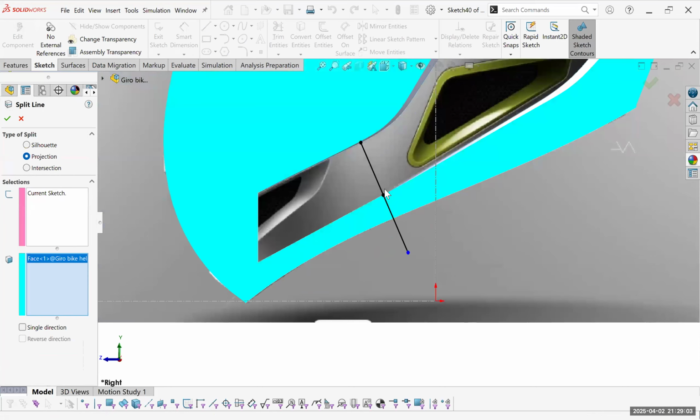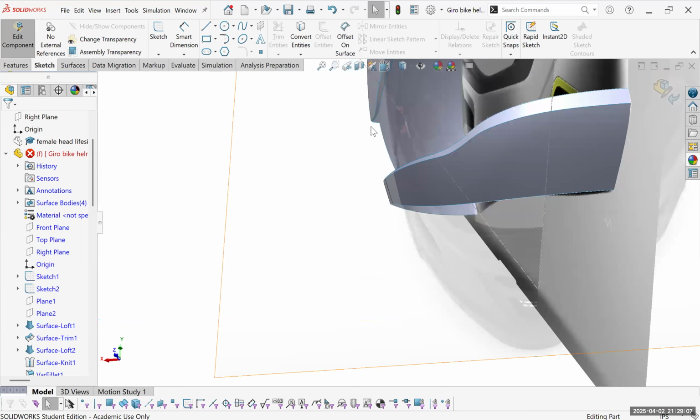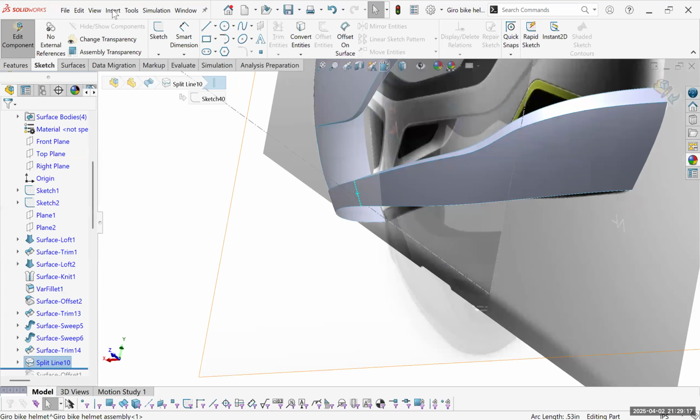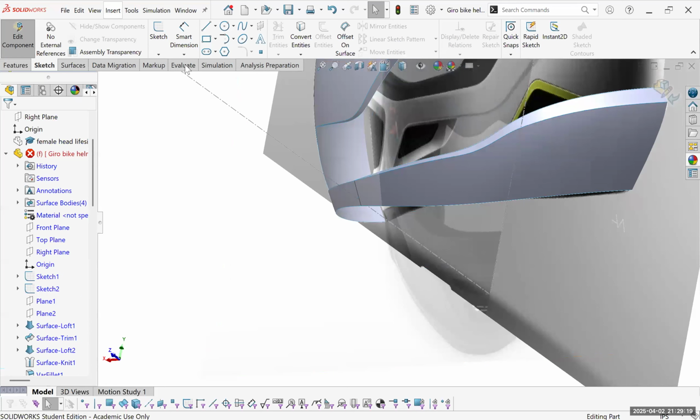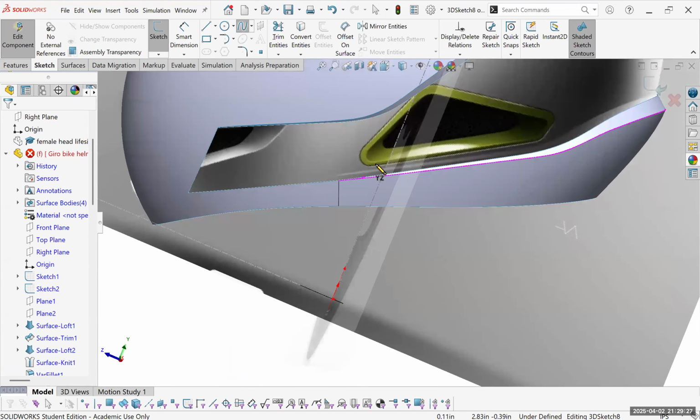You can see this is in a curve. So any connection curve I put in here, it needs to follow this. So that's why I created that edge. I can set a 3D sketch tangent to that. So now we'll go insert 3D sketch. We'll go to a spline and start at the end of this point to the end of our fillet.